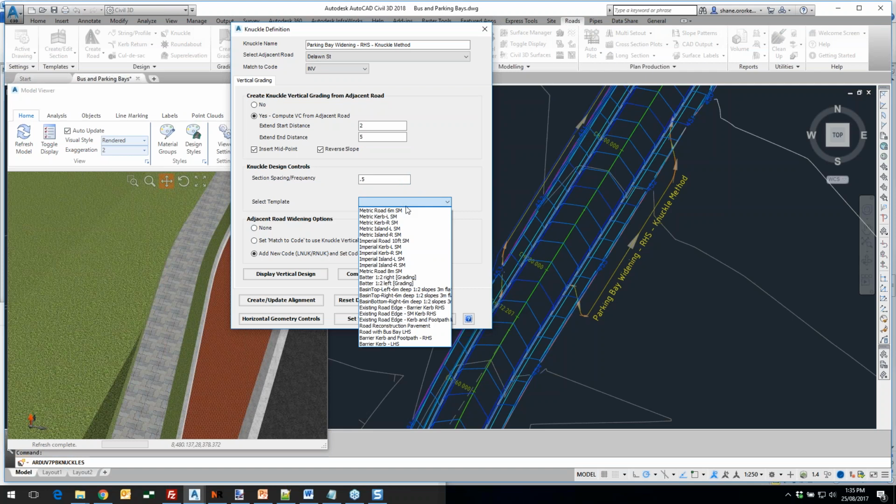So think about this. The footpath and the curb is going to get removed, as well as the batter for the road. And you're replacing it with a string that runs around here, has a code that touches the invert of the road, and you decide what happens to the outside of that string. So you actually want to put something on there.